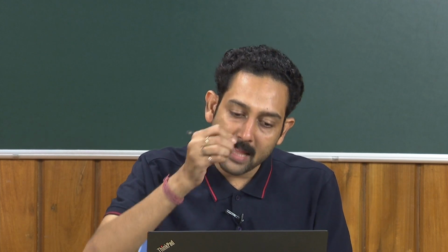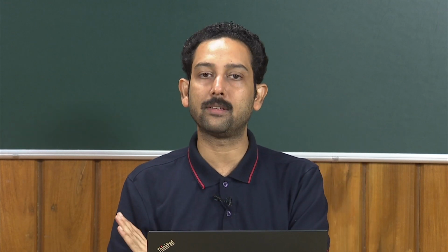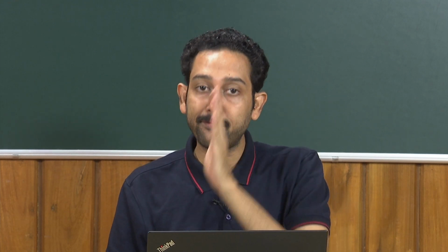So, what is a fault model? Fault model means they assume that there will be certain kinds of faults in the circuits which by statistics they have found out are the most likely to occur, and then you have to verify that those faults are not there. So, we are not even concerned about the functionality of the gates, but we assume that there can be certain faults which are very predominant and you have to verify that those faults are not there. If those faults are not there, we will assume that the circuit is operating properly. Again, this is an optimization to save time, but with a slight compromise in the quality of the test. But again, as I told you, by statistics people have found out that if you have a proper fault model, the accuracy with functional testing is 99.9 plus.